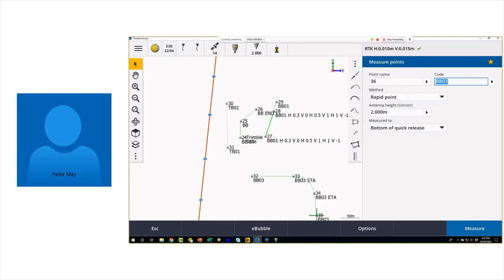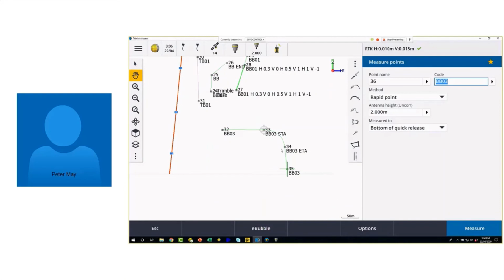For some government authorities, you're not allowed to do that. You'd have to actually take a lot of measurements with certain chord requirements. It really depends on the survey requirements that you're hitting as well. But even more generally, if you're doing open parkland, concrete tends never to be straight. You might just want a nice smooth curve that looks nice on screen. It plots better. It's a better representation of what's actually there rather than chording your measurements. And it becomes quite easy to do because it's active in the side panel. It's nice and neat. Once you know what the icons actually represent, then it's an additional function there.